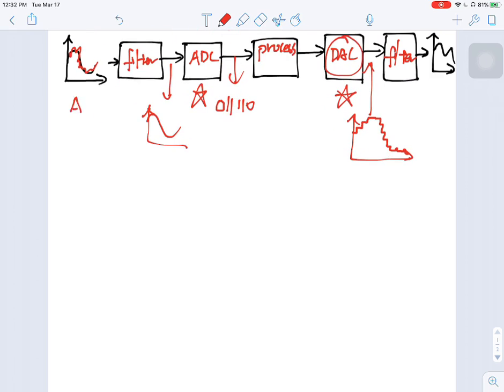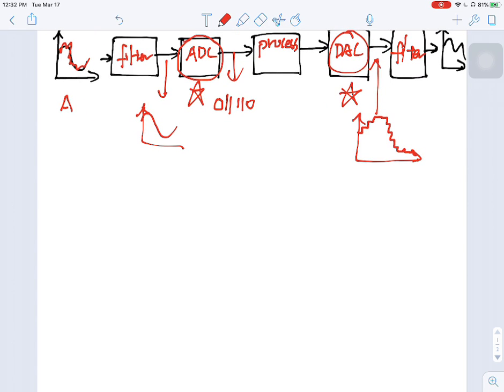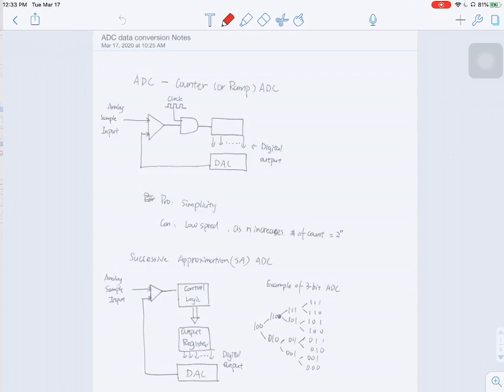So today we're going to move on to ADC, which is analog digital conversion. The reason we introduced DAC first is because DAC is simpler than ADC. ADC is much more complicated, and you will see that later. An ADC chip actually includes a DAC module inside. So we're going to look at what ADC is and the different types of ADC and their pros and cons.